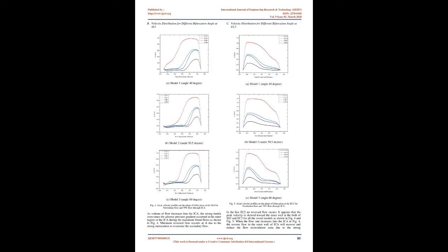And later, in the case of pulsatile flow, the large eddy simulation, LES, is used as the viscous model and the bounded second order implicit option is used as the transient formulation. In the pulsatile simulations, a total of 86 uniform time steps per cardiac cycle were used and the simulation was carried out over 6 cycles. The convergence was based on the residual in continuity falling below a prescribed value, 10^-6 for pulsatile flow and 10^-5 for steady flow. Under those conditions, differences in velocities between successive cycles were smaller than 10^-5.